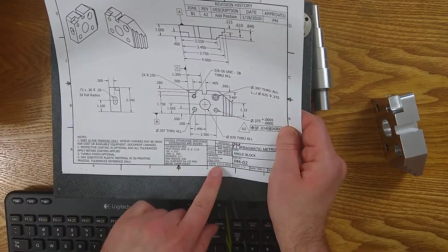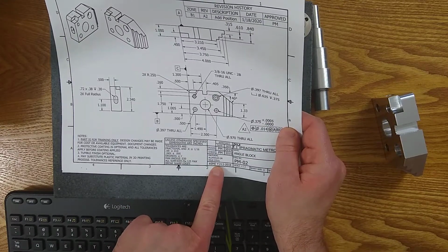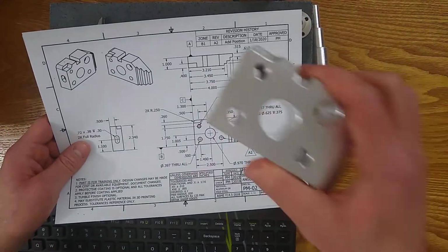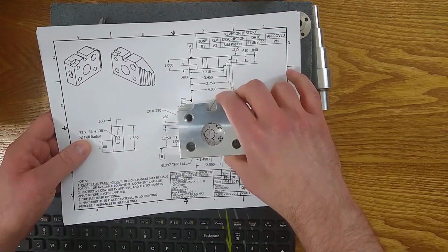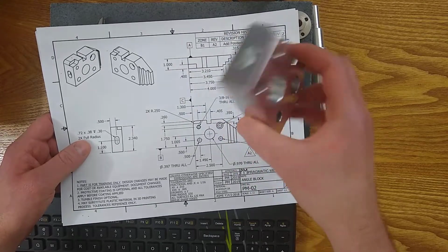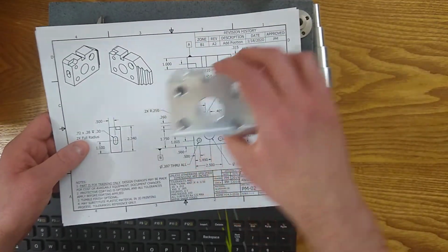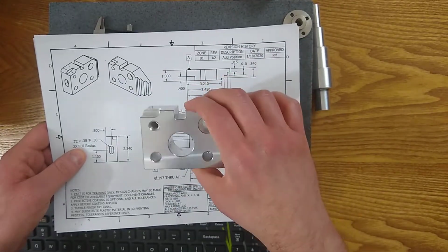And then number 2, when you have your title block, go ahead and review the standard tolerances, what GD&T standard they're using, what year it was called out, what scale the part was printed at. As I mentioned, I don't recommend you actually hold your part up and say, yeah, it looks good enough. That's not the point, but you can do that for a quick check to see if the part's finished, to communicate something. Look, I can't even get it to line up on the print. It's so out of place.